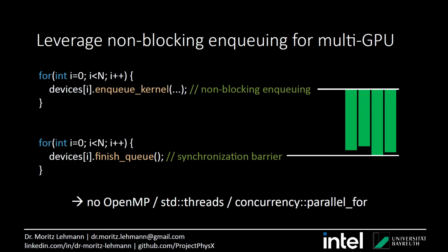For gravity or volume forces, which are basically equivalent to a pressure gradient, there's the so-called Guo forcing. That adds a force term to the collision operator, and it handles force per volume. There's also an extension to do thermal convection flows. That works by